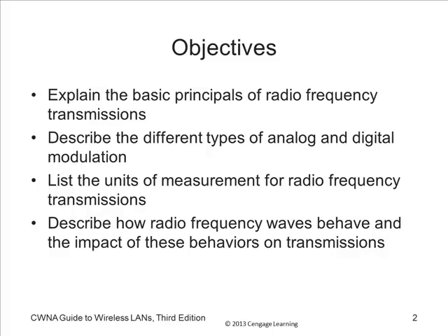I told you guys a story about the Persian Gulf. Our surface search radar should go about 20 miles to the horizon, 25 miles maybe. We could set up at Bahrain on some days and watch traffic in the Strait of Hormuz, which is 300 or 400 miles away. What do we get? We got some ducting, so the signal would just travel in the atmosphere without the absorption.